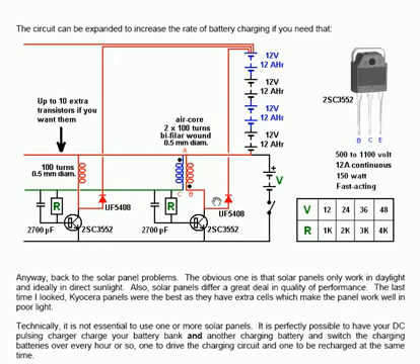That's the main basic circuit as shown before, but you can then add additional transistors on, taking the same signal from the blue coil and feeding it through the same resistor to the same transistor, using the same diode to feed on. You don't need the blue winding, you can just have 100 turns of 0.5 millimeter wire to duplicate the red coil, and you can have up to 10 extra versions of those.